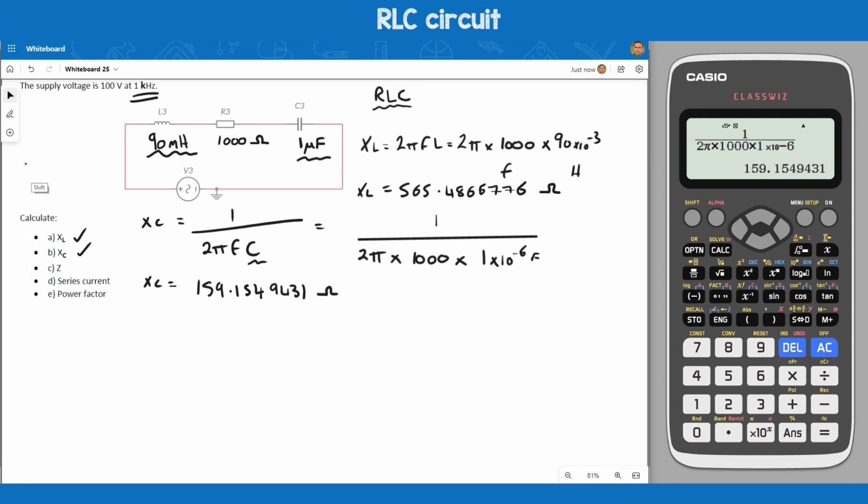So what we have is the resistance, the inductive reactance at 90 degrees, then the capacitive reactance at minus 90 degrees, and if XL is bigger than XC in length, then XL take away XC is going to mean that the impedance Z is up there.